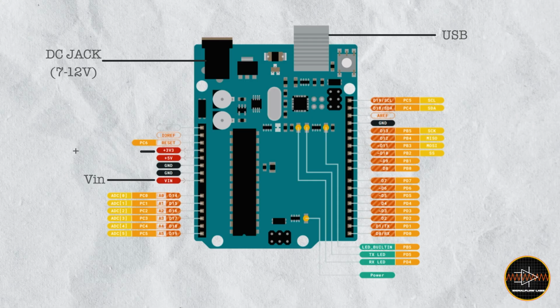There's one more regulator available on board, that is a 3.3 volt regulator. So it gives 3.3 volt output. As you can see on the pin diagram, there are 2 grounds available, 5 volts available, and 3.3 volt output. This 3.3 volt output you can give to various sensors, because every sensor works in a different way. Some sensors require 5 volts, some sensors require 3 volts. So in that way you can change accordingly and use it.